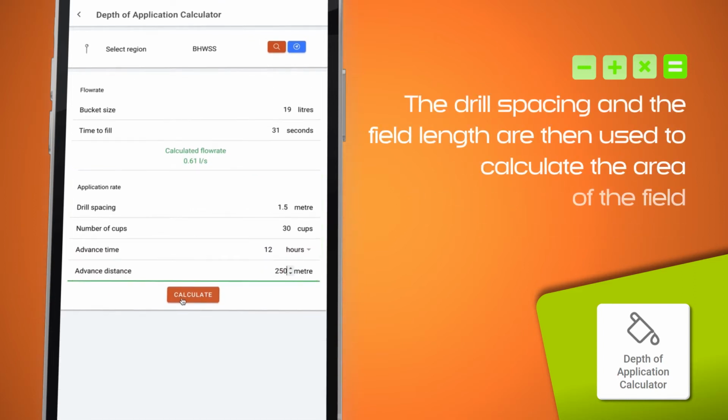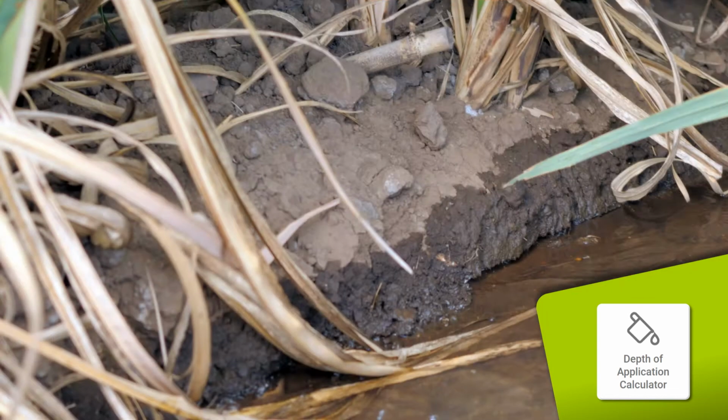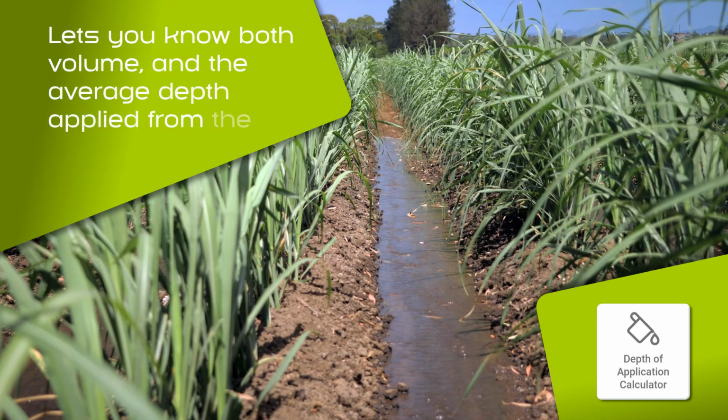The drill spacing and the field length are then used to calculate the area of the field. 1 litre applied over 1 square metre is equivalent to 1 millimetre in depth. And this tool lets you know both volume and the average depth applied from the irrigation.